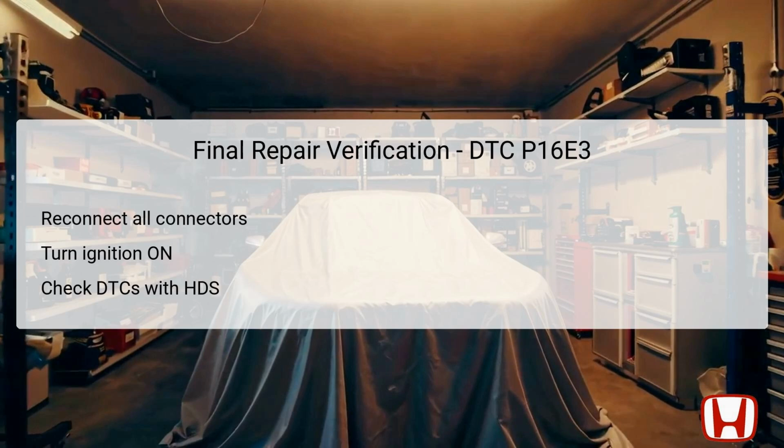Start by turning the ignition switch to the lock position before reconnecting all connectors to their appropriate locations, ensuring no connections are left loose or improperly seated. After everything is securely connected, switch the ignition to the on position to power the vehicle's systems. Utilize the HDS to check for any outstanding or new DTCs. Confirming that DTC P16E3 is no longer indicated suggests successful repair completion.